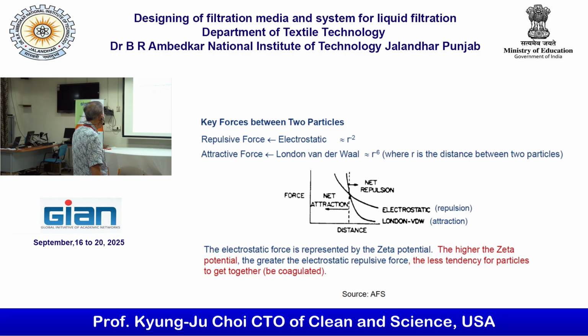So the higher the zeta potential, the greater the electrostatic repulsive force, and the less tendency for particles to get together. So you need to lower the zeta potential in order to make the agglomerate. That's why zeta potential is important.